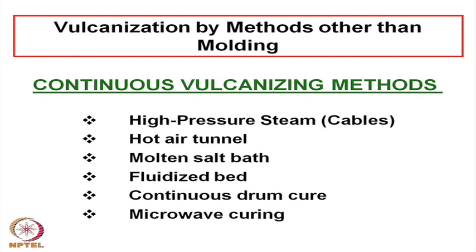Then it ultimately goes out of the tunnel. Then there can be a hot air tunnel, a molten salt bath, a fluidized bed, a continuous drum cure system, and also microwave curing. That means there can be a microwave chamber. If the product is introduced in that microwave chamber, that will cause curing or vulcanization.